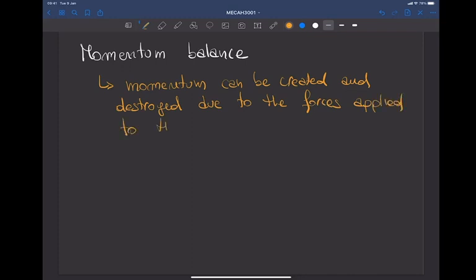Okay, so this is a very important consideration, because it means that in a steady case we cannot simply say that the momentum entering the control volume equals the momentum leaving the control volume. Because this difference will be equal to the sum of the applied forces to the control volume. First of all, we have to define what these forces can be, but even before, what is the momentum flow rate through a section, per unit time.